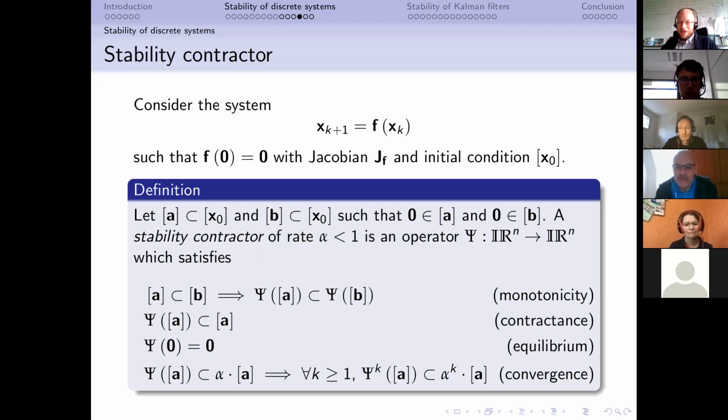Yes. And the last philosophical comment from my perspective is, when you place the observer dynamics within the closed loop, that's also something where you could show the closed loop dynamics stability in cases where the separation principle of control and observer design no longer holds. Again, for the nonlinear case.